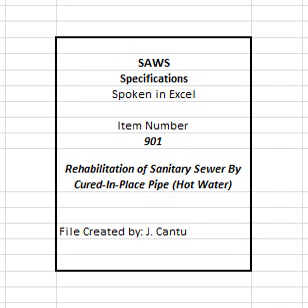C. After vacuum in the tube is established, a vacuum point shall be no further than 75 feet from the leading edge of the resin. The leading edge of the resin slug shall be as near to perpendicular as possible. A roller system shall be used to uniformly distribute the resin throughout the tube. If the installer uses an alternate method of resin impregnation, the method must produce the same results. Any alternate resin impregnation method must be proven.